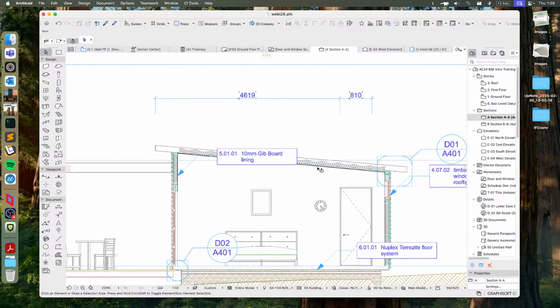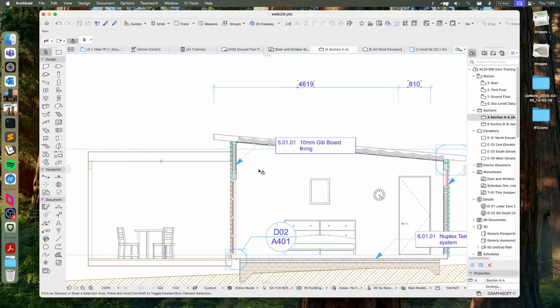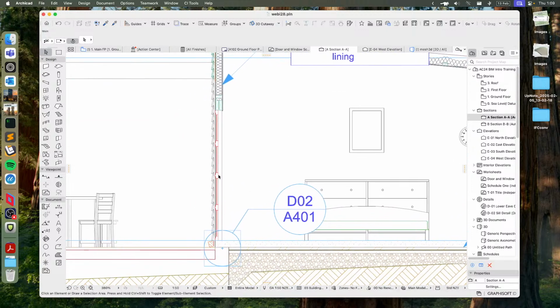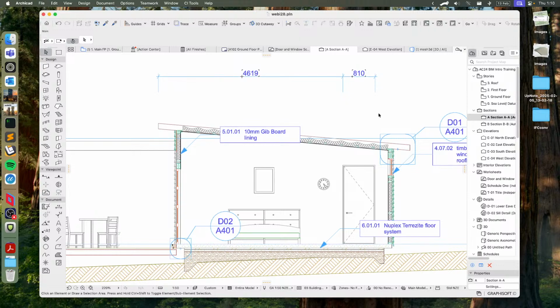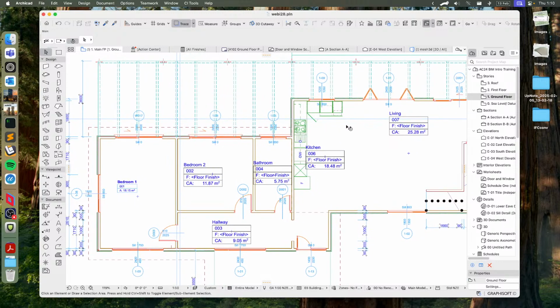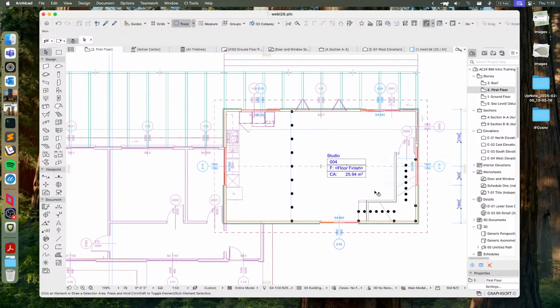So it makes not only the 3D views better, but all of your other model views will have all of that additional data as well. You can see over here on this side of the wall covering that because we included a sill in it, the sill is already done for us there as well. So that just makes it nice and easy. You don't have to worry about doing that sort of thing. And the roof covering works the same way. We're going to add a bunch of additional detail to our roofs, which will take care of a lot of that detail work for us, stuff that you would be doing in sections. The way that it works is very similar to how the wall covering works.